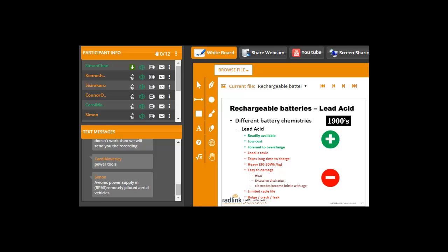Yes, so coming back to nickel-cadmium batteries, they're readily available. You can still buy them, and they're low cost. The best part about them, I think, is that they can be very, very rapidly charged, 1 to 2 hours to get to full charge, and they're able to deliver an incredibly high peak discharge current. So in the old days of the power tools, they were certainly the batteries of choice.